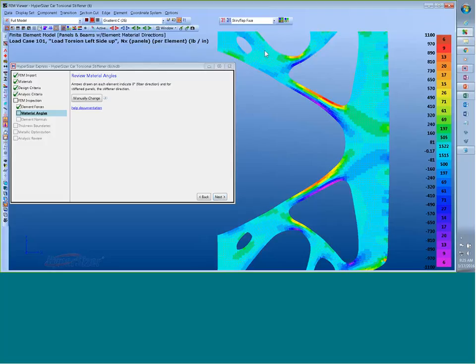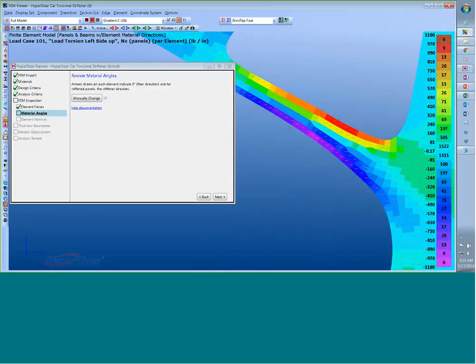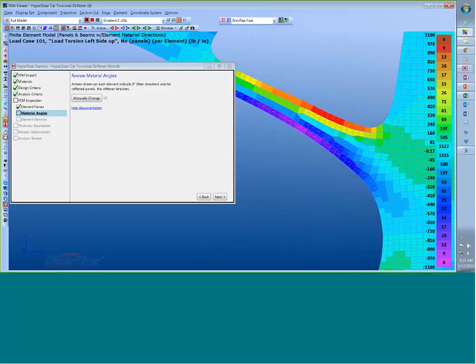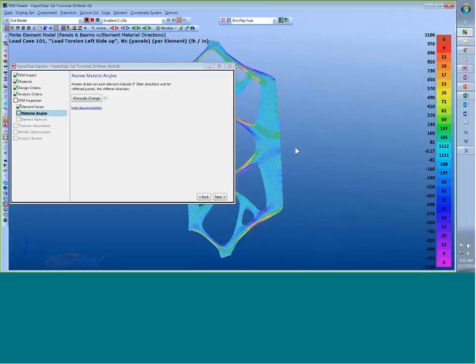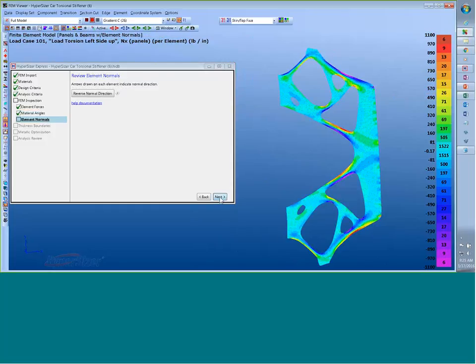Material axes are very important, and this will be a composites example, so you do want to know in which direction you're intending the unidirectional ply to be oriented. And for the aerospace guys, this is not your traditional tape material. These are like wide, 4-foot wide unidirectional layers where the part shape is cut out. So this would be indeed the zero axis for this part.